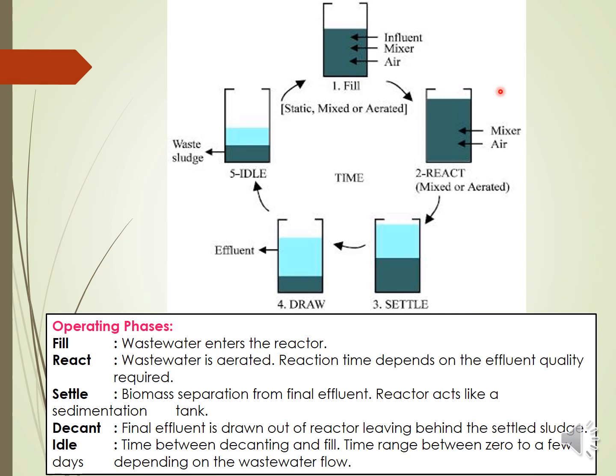Reaction time depends on the effluent quality which is required. And the third stage will be the settle. Here the biomass will be separated from the final effluent. As you can see, it is the same compartment, but we stop mixing, so we allow the wastewater to be separated, or we allow the sludge to be settled, and then decantation or drawing the wastewater out